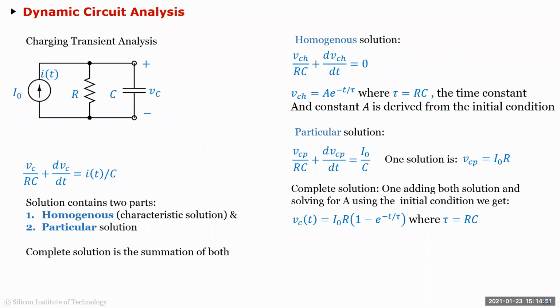So for example, your zeros will change if I have one network and I change the input voltage source to a current source, it still is RC. Okay, time constant doesn't change, but my output voltage step will change now. And if you talk in control system or signal theory language, your zero is changing, but your pole tau is still 1 over SRC. Okay, so always remember that.